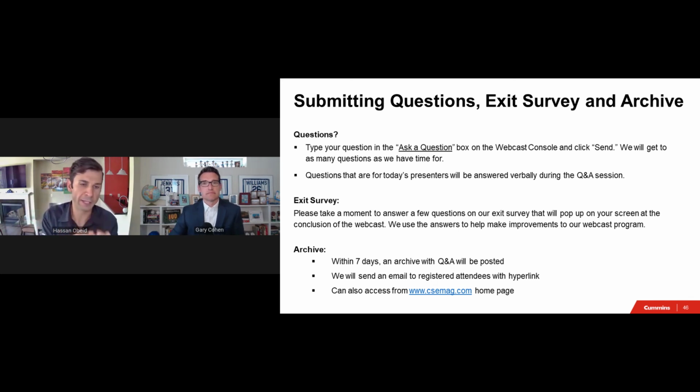If the label lists the WCR at 480, you cannot use that number at 600. And you cannot use Ohm's law or any other law to calculate it. It has to be tested, unfortunately. So you cannot just simply call the manufacturer and ask for that number. It has to be tested per UL 1008 and has to be published on the spec sheet.